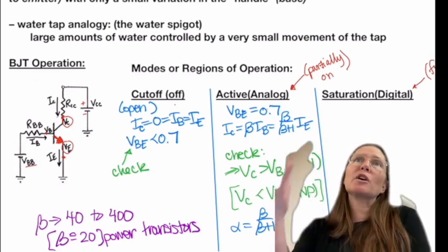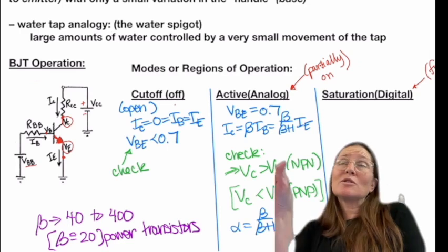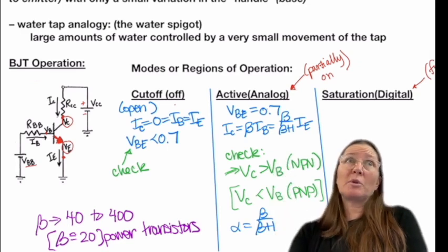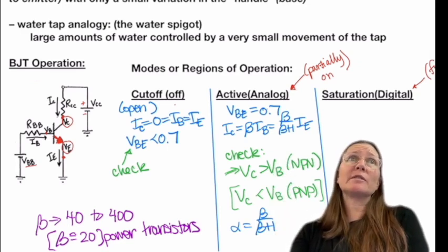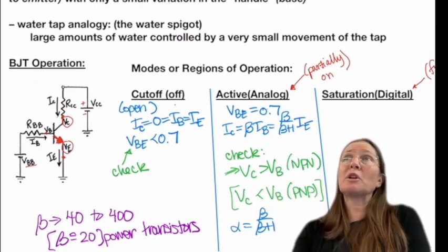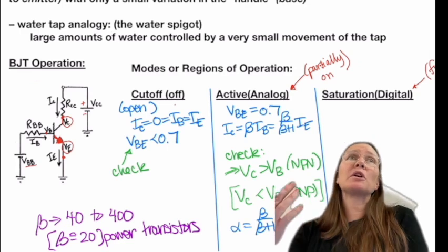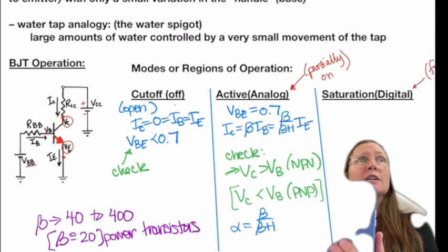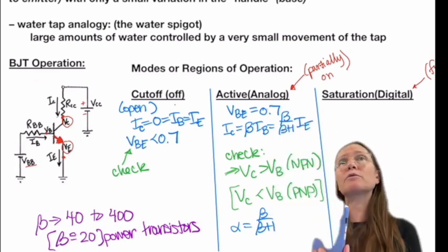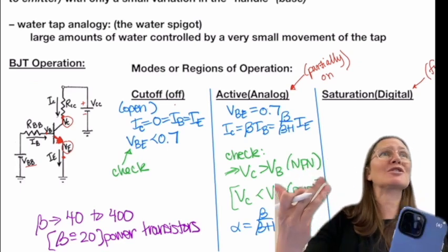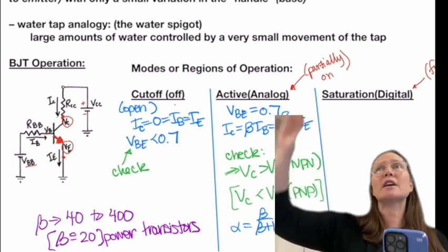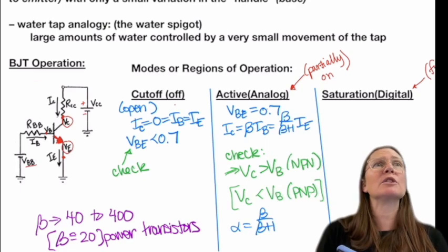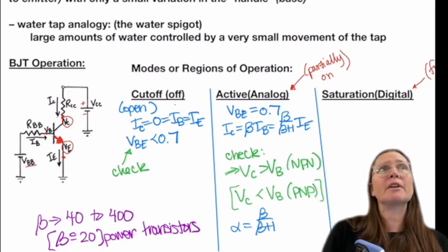So if I put 1 into the circuit, it is actually multiplying all those electrons. If the beta is 100, it's multiplying them by 100. If it's 400, it's multiplying it by 400. So it has to do with the doping in the material itself, to say, what is that amplification of whatever I put on the base? How much is it amplifying into that collector side?